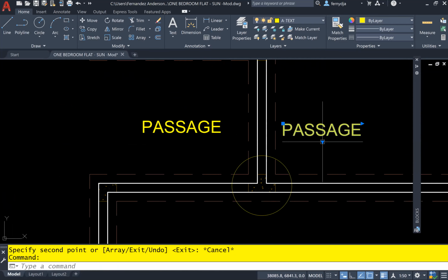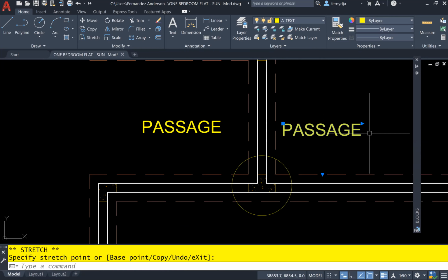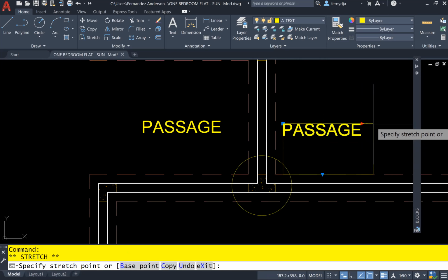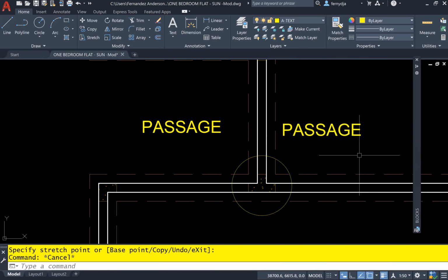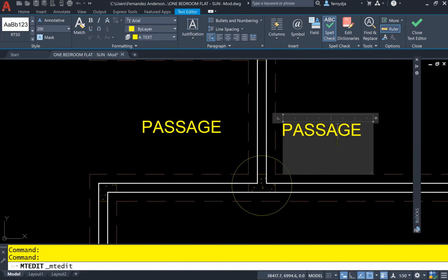Select it once, and I'm going to resize that to accommodate more than one row and increase the width a little. All right, so to edit now, we know we can just double click to select the text to go into the edit mode. But if I double click again, it will also select the text, and then I could just type over it. So C, stiffener.